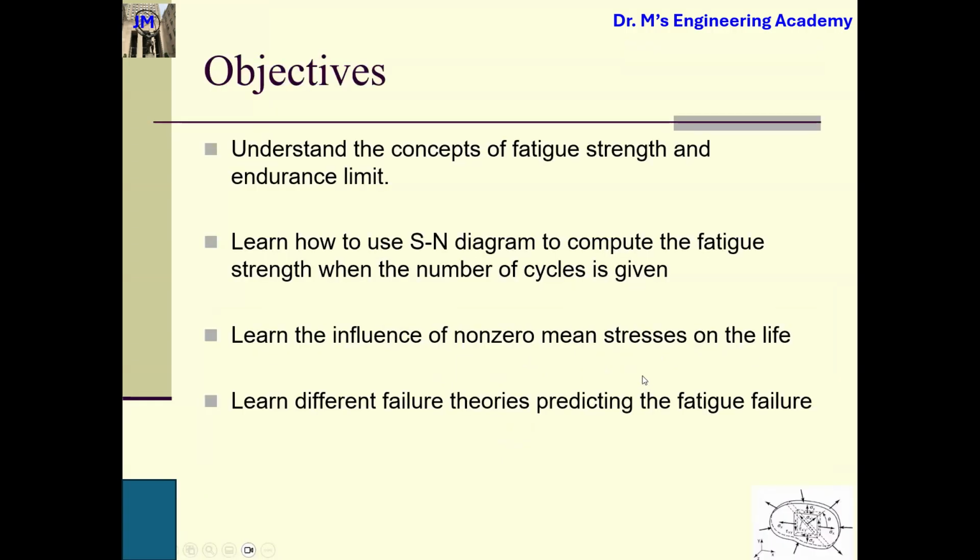So here are today's objectives, and we want to know the concept of fatigue strength and endurance limit. Do you have an idea about fatigue? You know fatigue, right? Okay, and so learn how to use the S-N diagram. S stands for stress, and N stands for the number of cycles. Write it down. S means the stress level you apply, and N is the number of cycles that you can have before the specimen fails.